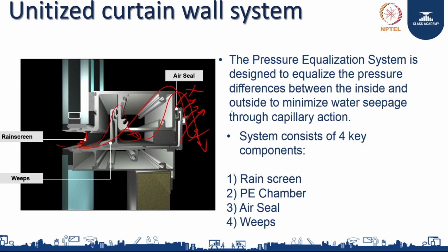It can rise several floors. I have personally seen a lot of failures where you can see water rising 2-3 floors inside a joint. So, whenever you design anything in facade, make sure your air seal is proper and tight.